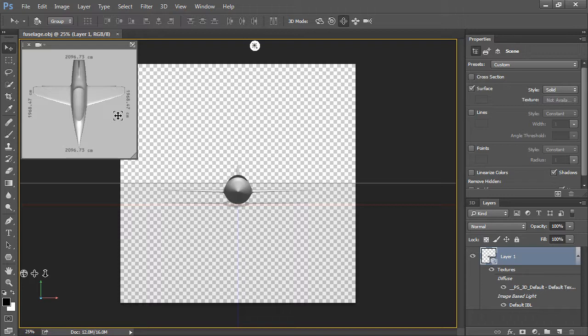However, we can zoom the 2D canvas, the viewport as it were, in and out, and that will not be an issue. Once again, our canvas needs to be large enough to enclose the entire object at once at the resolution of the final texture. Therefore, our viewing canvas should be a square with sides equal to or larger than the longest side of our final texture map. Cool, we've got that loaded in.